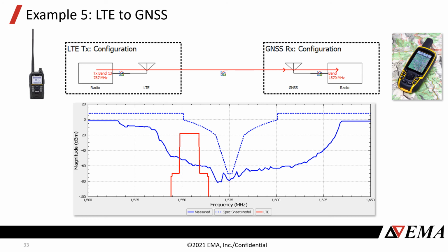And so in the video I'm about to show you, Juan establishes a carrier to noise metric for the receiver of about 40 dB. And then he turns on the LTE modem, and we look at the LTE harmonics, and you'll see them jumping around in frequency, and you'll also see degradation in the carrier to noise as those interfering signals are introduced. And again, I show a plot down here. So again, keep in mind, LTE is not a fixed frequency. This is actually moving around in frequency.